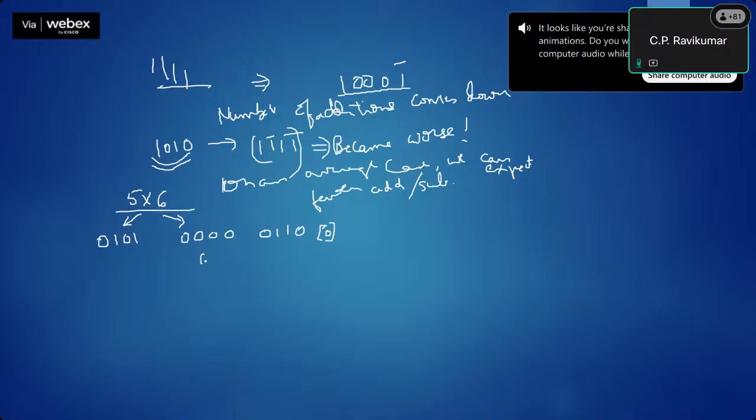So we shift A and Q. If you see a 0, 1 like this, that means you have to subtract. So here I have 0 and I have to subtract 5 from it. So 0 minus 5 is minus 5. It's a signed multiplication. So minus 5, you may remember, is 1, 1, 0, 1. This is minus 5. And this remains 0, 0, 1.